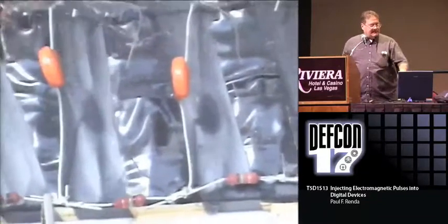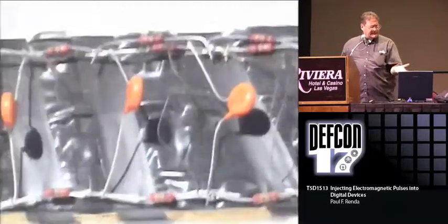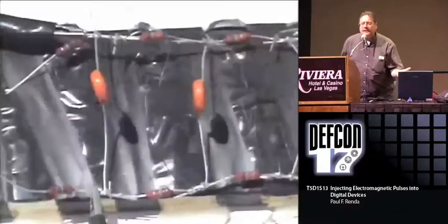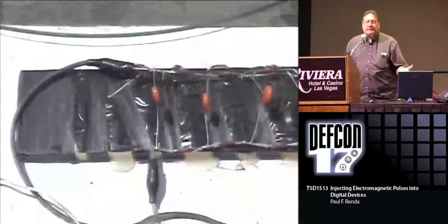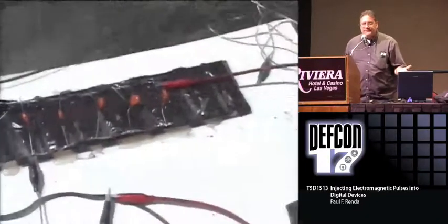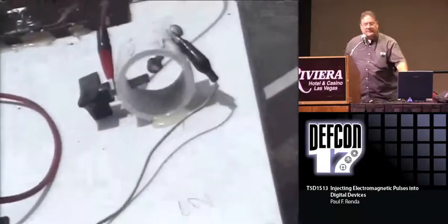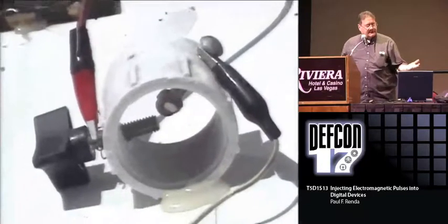Right now I'm showing you a wire that they discharge through. They discharge in series. If each capacitor, I have, what would I have, 5, 6? Well, let's say 5. If each capacitor charges to 5,000 volts, and I have 5 of them, I have 25,000 volts in series. And it's discharged through this spark gap, which you already saw before. Just PVC pipe, 2 conductors.